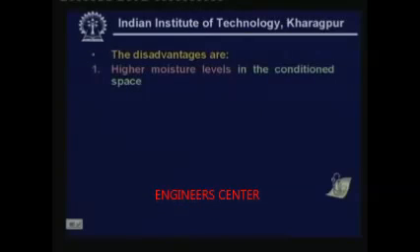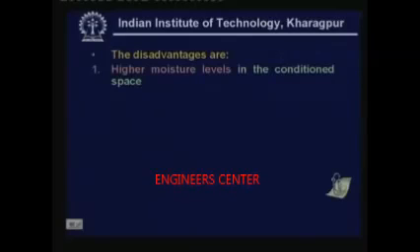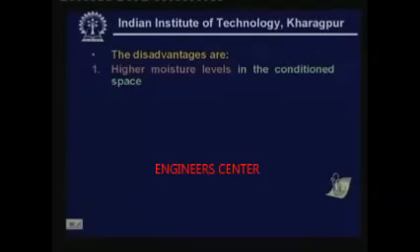However, these systems obviously have some disadvantages. What are the disadvantages of these systems? The first disadvantage is higher moisture levels in the conditioned space, because the air that you supply to the room is at a much higher humidity ratio. So the moisture levels in the conditioned space will be higher.